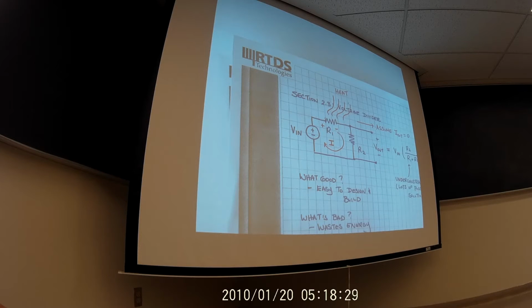There are 2 laws that stick out right away that you should be able to use to define V out. One would be KVL, and the other one is KCL? Ohm's law, exactly. Ohm's law. KCL really doesn't help us find voltages, at least directly. So let's try writing that out.